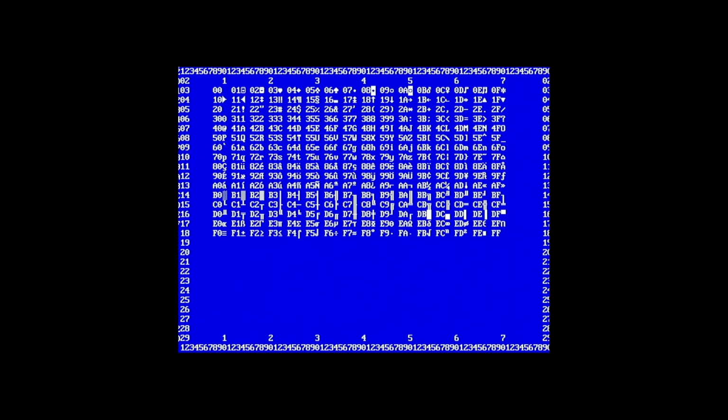And if I go in and put 20 into that same value, so if I just go in here and go to memory 00 D6, if we put 20 in that and then we run that, it should turn the cursor off. There we go. So in fact we've successfully turned the cursor off there. So I'm just going to set that back to what we had it before. So there we go, we have the cursor back again. So we've done the cursor, however it's not quite right yet, so until we sort out the rest of these timing signals, then we need to come back to that and make sure that it's working properly later.